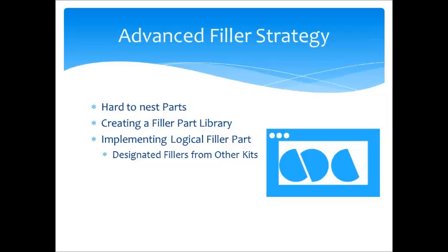In the case of logical fillers, there's a variety of things. One of the tricks that can be used is if you're doing kit nesting and you have kits and you know that all of the parts belong to this kit, you can, in fact, redefine your kit and allow some of those parts that are really good fillers that you use a lot of, brackets or whatever they may be that are common parts for you, and you might want to take them out of the kit definition and move them to the filler part library definition.